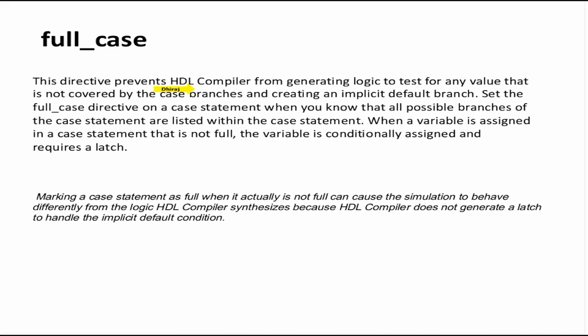You obviously do not know this. So what is the way out? The first way out is to correct your code. Use a default statement. Make sure that your case analysis is complete and you mention all the cases. But many times it's not possible. Many times the designers know that the input case will never come, so they don't code it. Then to prevent a latch, you can say synopsys full case in front of the case statement, and DC will now not infer a latch. We will see 2 examples.